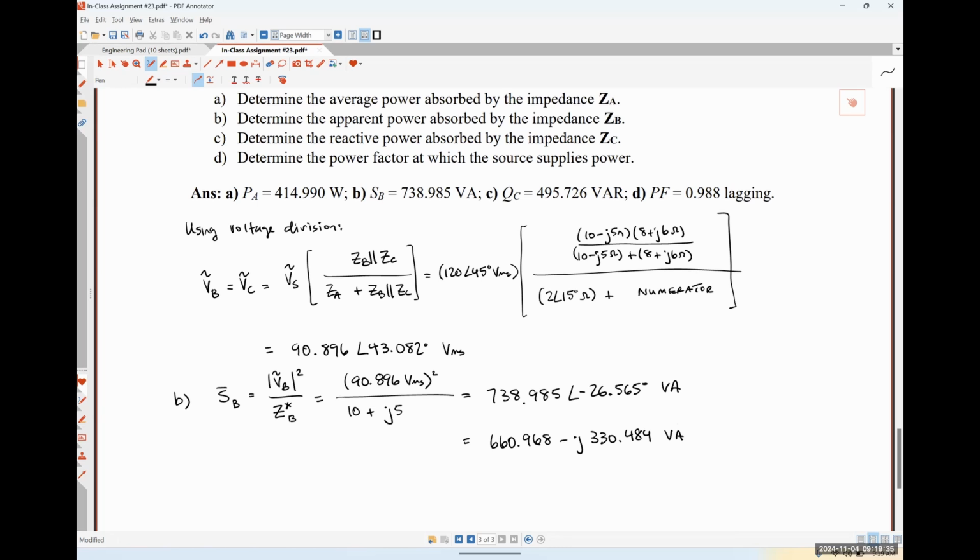We were asked to determine apparent power. So which of those four numbers is the correct answer? Apparent power is the magnitude of the complex power written on the board, for what it's worth. Right? So the part that we're looking for is actually this guy right here with units of volt amperes.